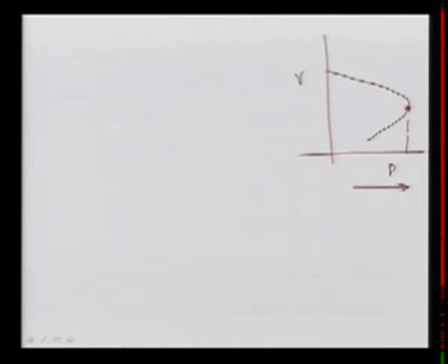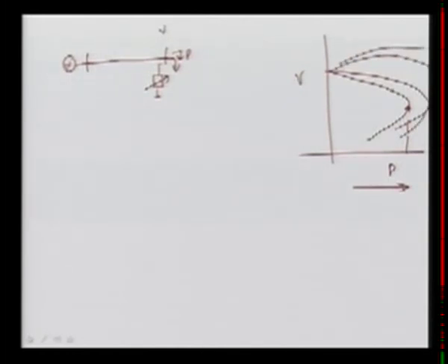Now if we use compensators, let's suppose you have a generator, here your transmission line, this is your load, and if you use some compensator here, that is a shunt compensator, it may be your SVC or STATCOM, that is variable. So that is the P that we are drawing here, and the voltage at this bus we can maintain. Let's suppose you go for leading, if you are injecting reactive power, your curve will be like this, and it may go like this. So this is leading power factor.